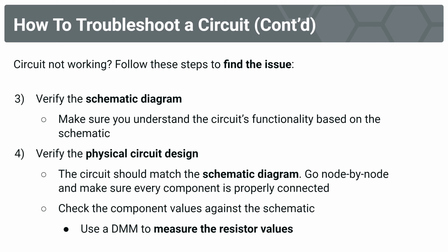So the third step would be to verify the schematic diagram. You've got to make sure you understand what the circuit is actually supposed to do. In fact, maybe you expected the circuit to do something different from what the actual schematic said it would. And in fact, the circuit was working the whole time, you just didn't understand it quite right. Or, when you verify your physical circuit design in step 4, you find that the circuit doesn't actually match the